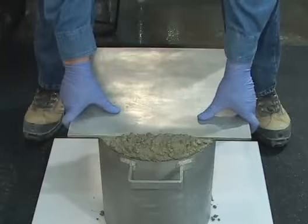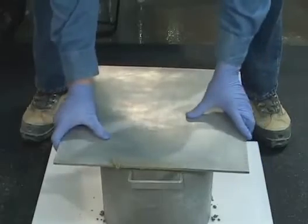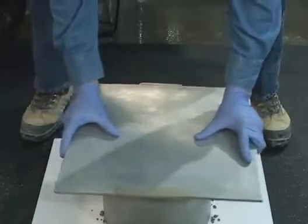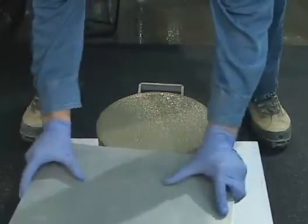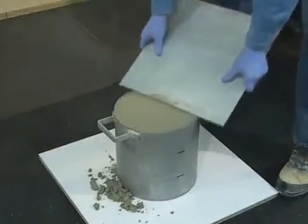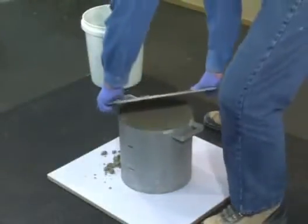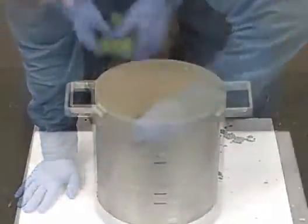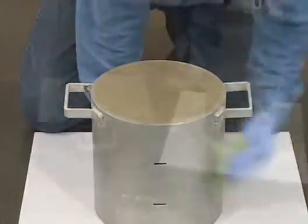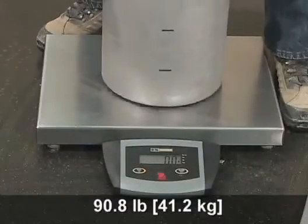Return the plate to its original position. With downward pressure and using a sawing motion, advance the plate completely across and off the measure. As before, keep the plate level at all times. With the plate inclined, use an edge to produce a smooth finished surface. Now completely clean the exterior of the measure. Then, determine the mass of the filled measure and record this value.